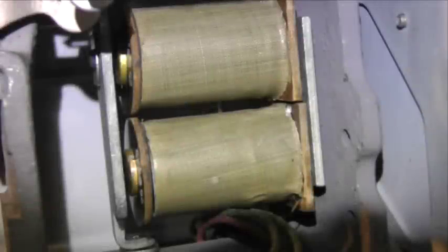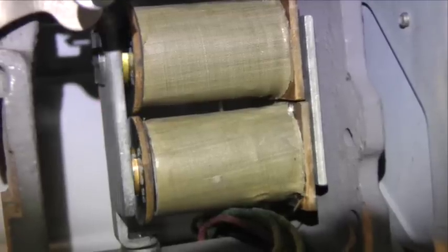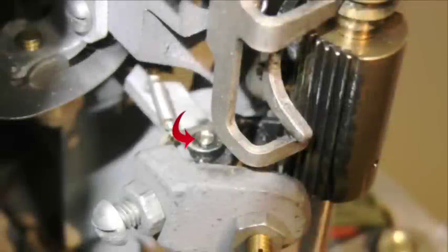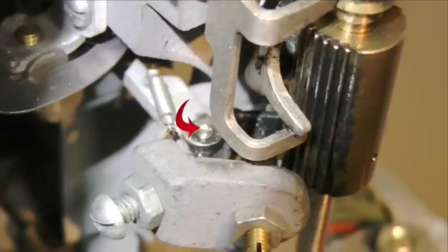The energizing path for the rotary magnets is closed at the same time as the operating path for the E relay. As a result, the rotary armature now operates. The rotary pawl is attached to the end of an arm of the rotary armature. When the rotary armature operates, its pawl engages a tooth on the rotary ratchet, which forces the ratchet to rotate clockwise one step. Of course, the shaft and all of its attached apparatus also rotate one step.